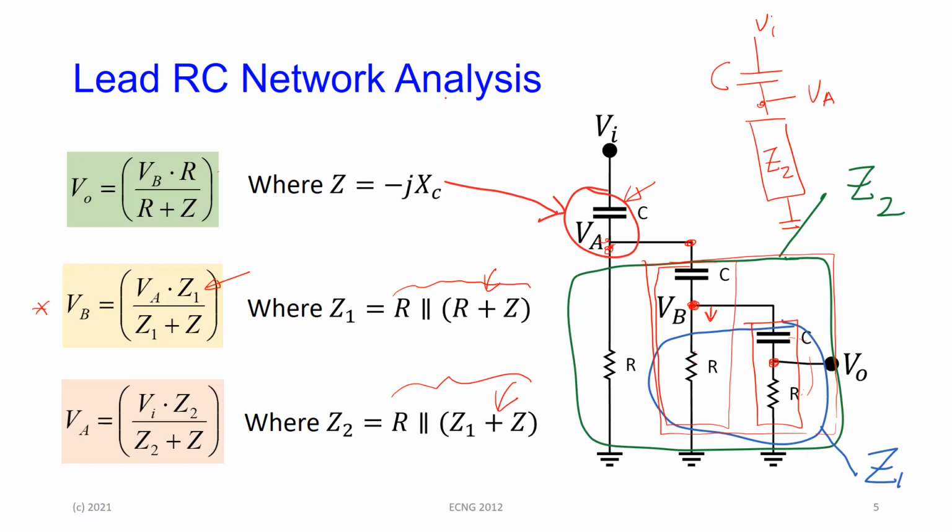So it was like what I drew before, if you think about it in terms of resistor networks. Something like that. We're taking our voltage coming out here. So here is a normal resistor potential divider. If you look at this second leg, at this point we have this leg in parallel with this leg. Once you calculate that, you have another potential divider here. Then here, seeing this in parallel with this, in parallel with this. We already calculated this from before, so it's basically this in parallel with that, and that gives you another one. Then you have the answer here. So you work backwards from the output to the input.